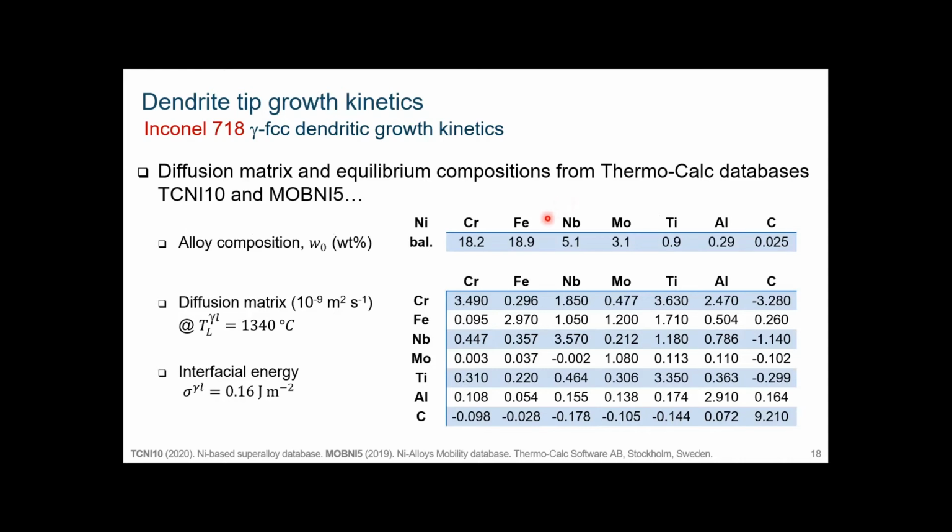It's far from being a dilute alloy, so we have to be careful, and this is the advantage of using Thermo-Calc for all this coupling. You don't need the dilute solution approximation which you find everywhere.